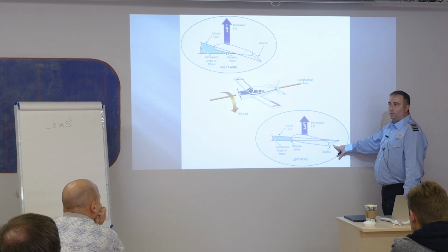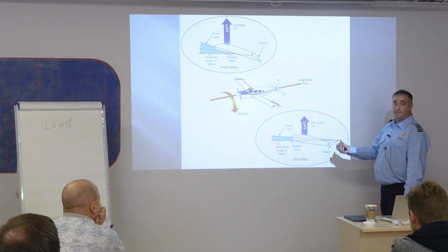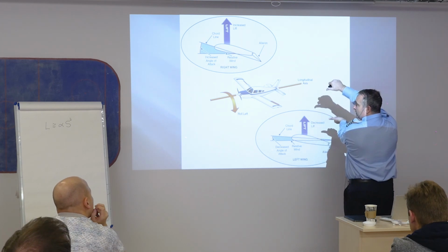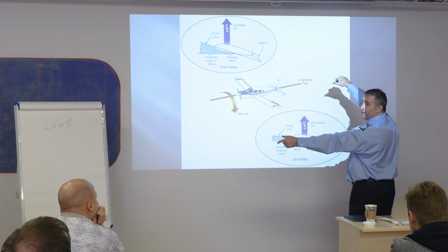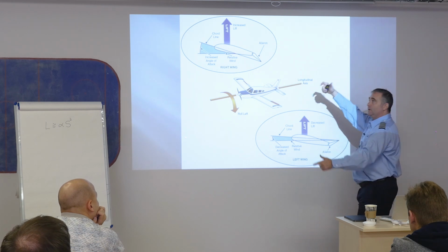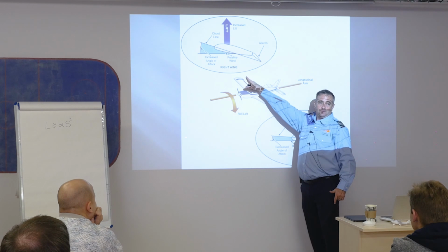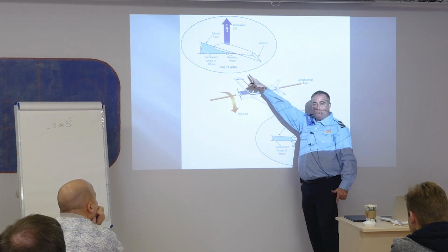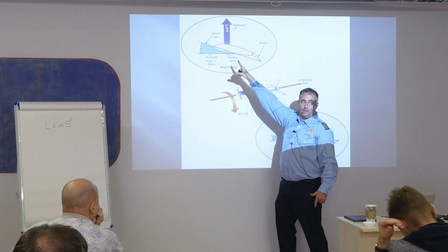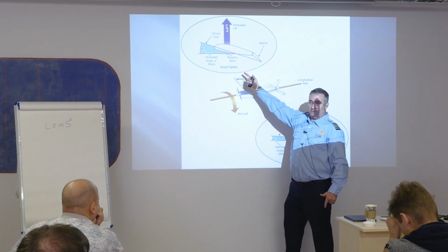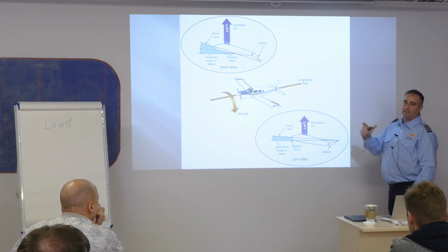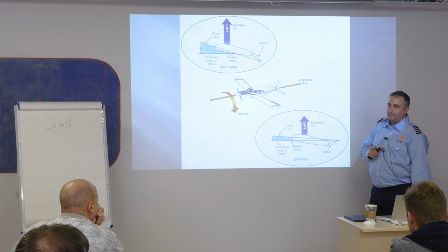Okay? So let's think if that makes sense. It should. I'm going to take my ailerons and move them to the left. I get less lift over there. Is that what I want? Of course. That makes sense. Okay. Here's where it gets interesting. The right wing is going to make more lift because the aileron goes down, which adjusts the chord line. That increases the angle of attack, causes more lift. And what do I get every single time that I create more lift? More drag.